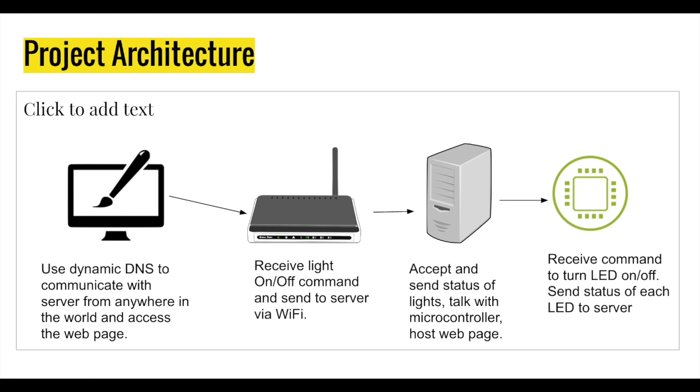On a very high level, our project works by interfacing the Arduino microcontroller to a Raspberry Pi server wirelessly using XBee. The server powers the front end and collects user input from the front end and passes these commands to the Arduino. It also fetches the status of LEDs from the Arduino, allowing us to view an up-to-date state of the system even if we change browsers or refresh the page.